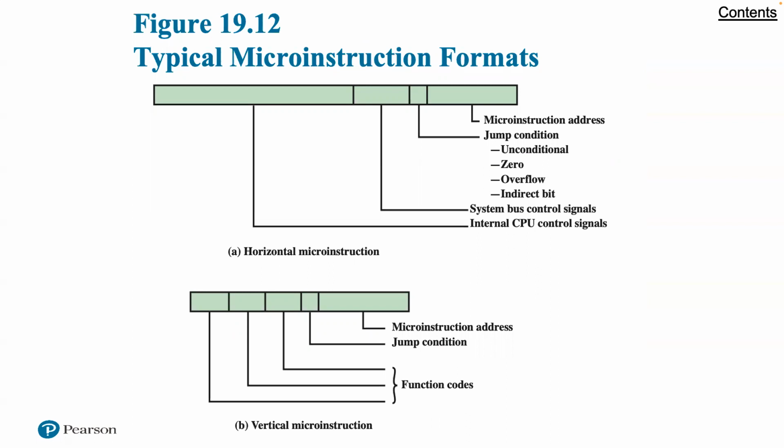How can we use the concept of microprogramming to implement a control unit? Consider that for each microoperation, all the control unit is allowed to do is to generate a set of control signals. Thus, for any microoperation, each control line emanating from the control unit is either on or off. This condition can, of course, be represented by a binary digit for each control line.